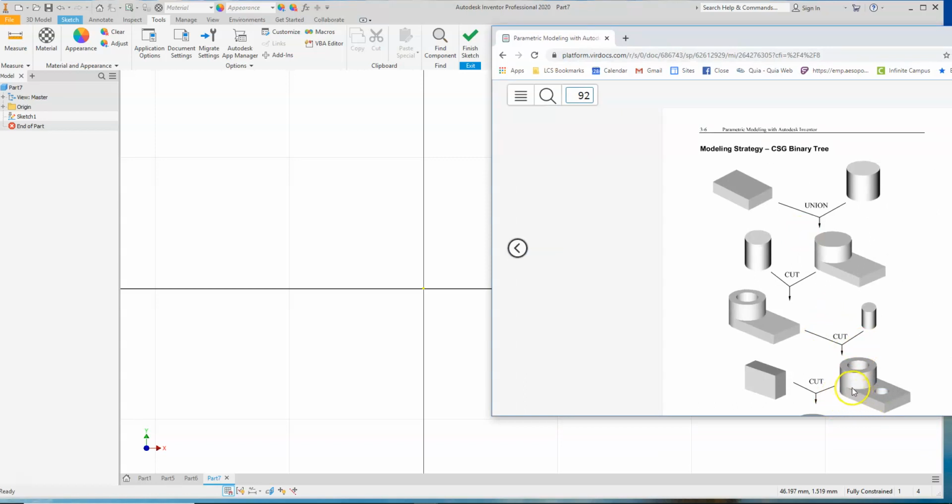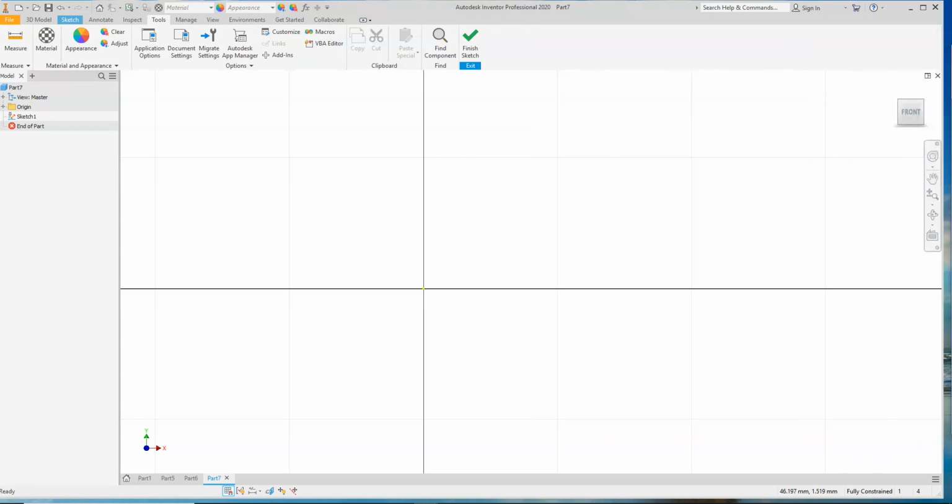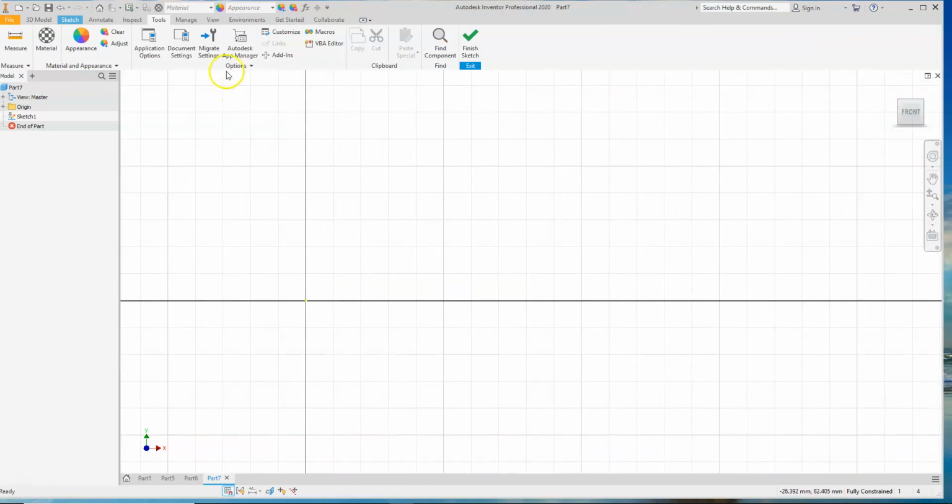So the very first sketch that they complete has the dimensions of, I think, the 75 by 50 rectangle, and I want to sketch this as the 75 by 15, and then extrude it into the z-axis at 50. So that's just a little change I'm going to make, so that my front view lines up with the picture that we have here, and I just plan that a little bit differently.